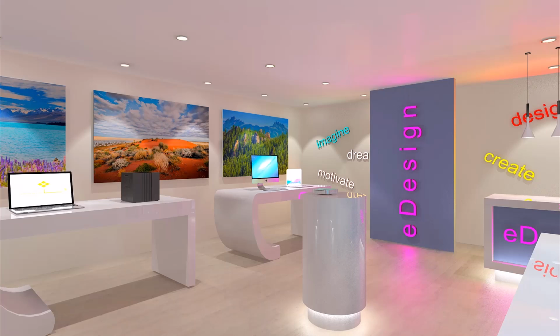Once the render is complete, use effects to make the visualization more lifelike by adjusting values such as brightness, contrast, saturation, and white balance. At the end of the process, enable the Sharper Details function. By enabling this, we will achieve an impressive effect and be able to create much sharper, more detailed images. Those who follow what they have learned during the workshop will be able to create high-quality photorealistic visualizations. However, rendering requires a lot of learning and experimentation, so it's worth practicing and experimenting with material settings and rendering.